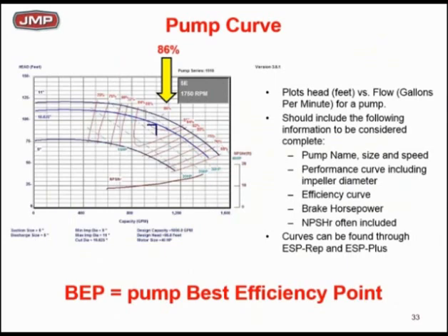And we're going to say two-way valves. We're going to say it's a low profile, and as that low profile changes, I'm moving back and forth on that pump curve. Makes a little sense, I hope. So we want to look beyond BEP. BEP's important. Didn't say it's not important. It is important. But we've got to look beyond BEP.